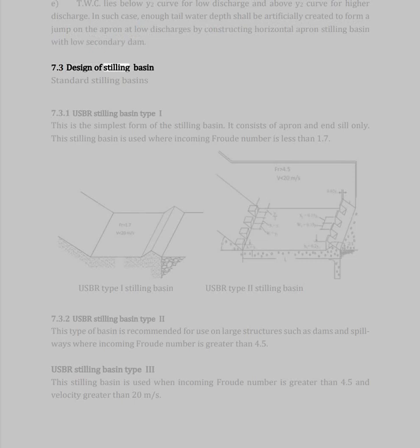7.3 Design of stilling basin. Standard stilling basins. 7.3.1 USBR stilling basin type I. This is the simplest form of the stilling basin. It consists of apron and end sill only. This stilling basin is used where incoming Froude number is less than 1.7.